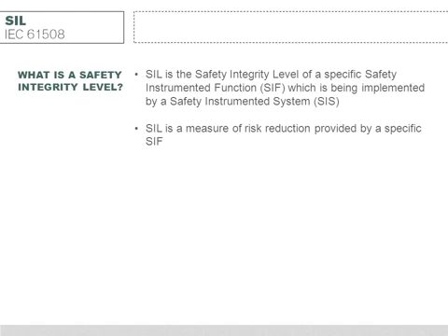So what you have is the system and the conditions that it is exposed to or has to operate under, and that will dictate what the necessary SIL value needs to be of those safety instrumented functions underneath of it.